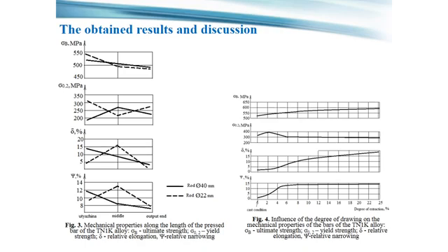Metal overheating was observed. The quality of the bar with a diameter of 22 millimeters is similar to the bar with a diameter of 30 millimeters. It's about 40. The mechanical properties along the length of the rods are quite uniform. This is shown in figure 3. With an increase in the degree of extrusion, the values of strength and plasticity increase, which is associated with grain grinding.